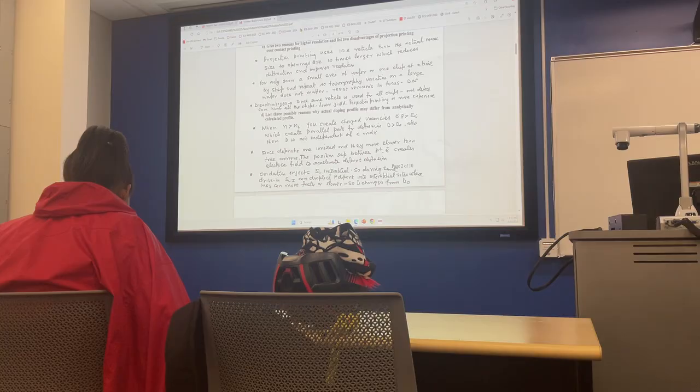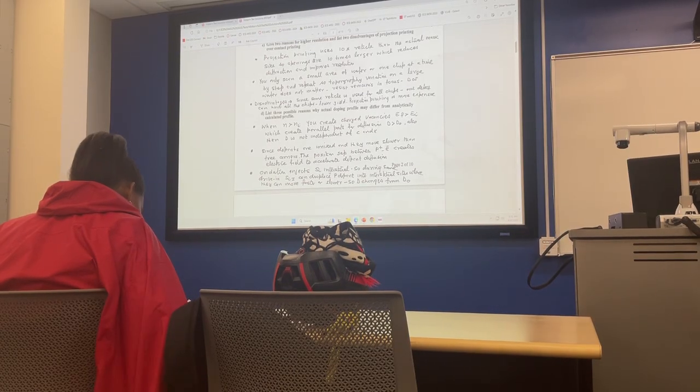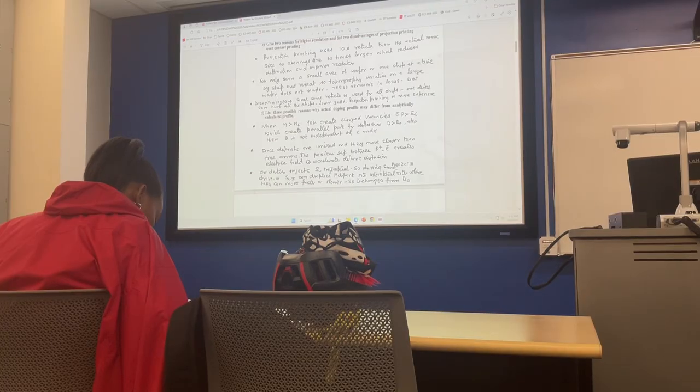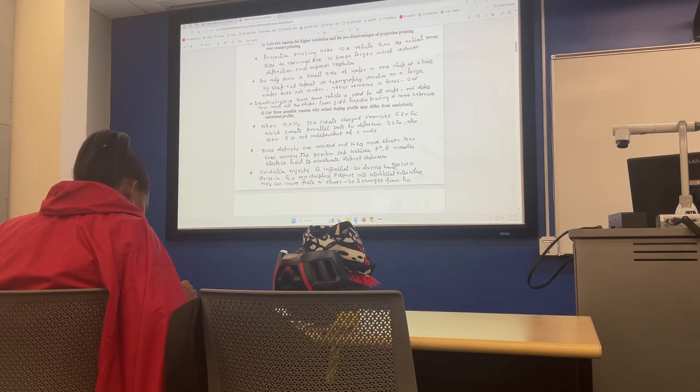And then the fourth thing we talked about is that there is a segregation coefficient at the silicon dioxide interface. So when it distributes, if you got phosphorus, it piles up at the interface. If you got boron, it depletes at the interface, right? Because the segregation coefficient has to be met. So those are four reasons.